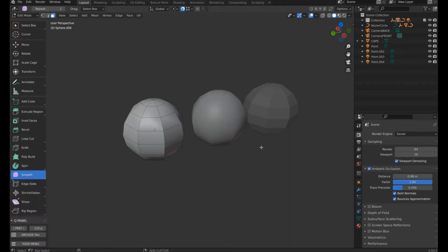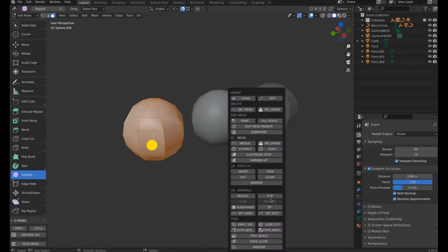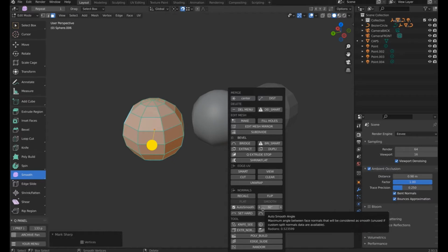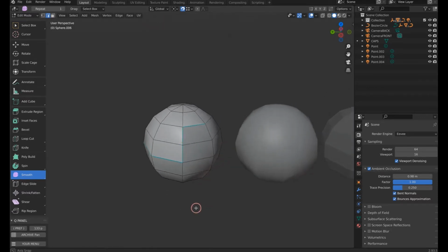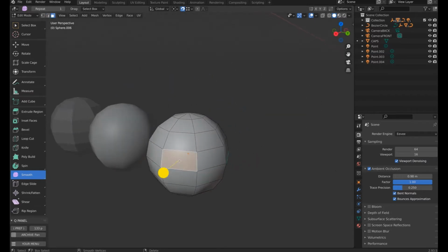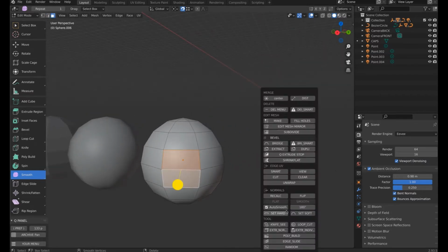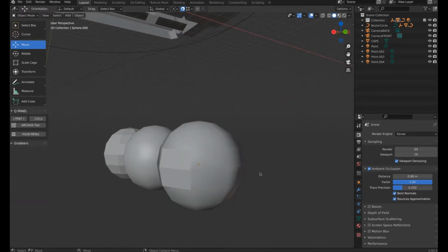But if you select all the mesh and set it to hard, it will ignore this value. And if you hit soft, it will follow this value. So if we drop to 180, we can still select some part and apply a hard normal, or select some faces and apply one hard normal.